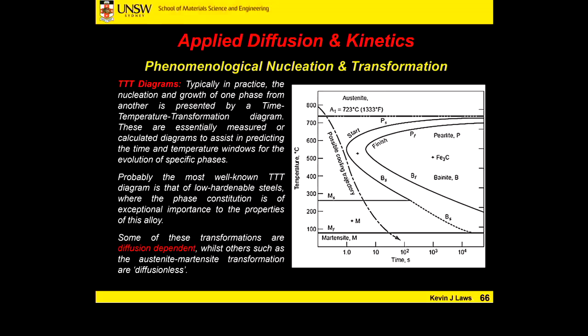So you might know when we have a steel, low or high carbon steel, specific steel, if we cool it very, very quickly, we can get other things occurring, can't we? Yeah, we can get metastable transformations. Okay, martensite or bainite forming. The steel system itself goes from a high temperature phase, an FCC phase, and when we hit about between 800 and 700 degrees, we get a transformation from austenite, FCC, to ferrite, BCC structure. So even solid state transformations we're plotting on these diagrams.